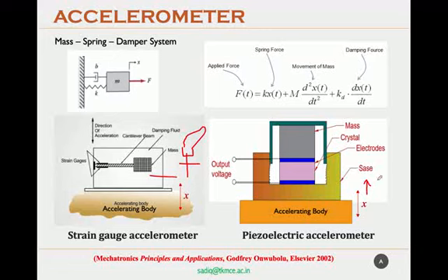Now we have seen acceleration sensing by sensing the movement of a proof mass. How can this be utilized to sense vibration? We know that vibration is a time-dependent function where the displacement of a mass varies with reference to time. So in the same arrangement, when the body moves in the upward or downward direction with reference to time, there is a change in the voltage that is given out. That change in voltage with reference to time is an indication of movement of the mass upward or downward, depending on the momentary direction change during the vibration.